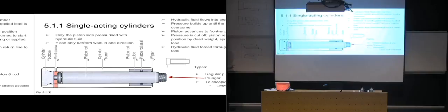And then the last part of the telescopic cylinder, the part here, starts moving outwards until it hits the end of the barrel. So then you suddenly have a stroke that is almost 2 times farther than what a regular cylinder would have had with the same length.